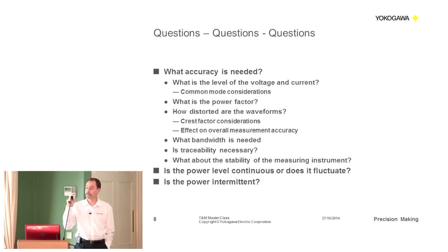Standard oscilloscopes are single-ended, of course. They are ground referenced, except for instruments like our scope recorder, which have isolated inputs. Because you've got floating voltages, particularly on three-phase supplies, you have common mode issues, where common mode voltages will affect the accuracy you're measuring. So that's also something you potentially have to think about.